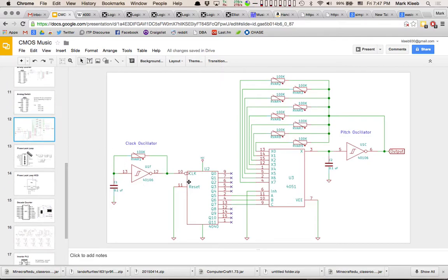Yes. So typically, Eagle parts don't look like the chip. See, this is in order, Q0, 1, 2, 3, 4, 5, 6, 7, 8, 9, 10, 11. That's not how they are on the pins, right? That's actually 9, 7, 6. You can see them labeled here. That's the actual pin number.